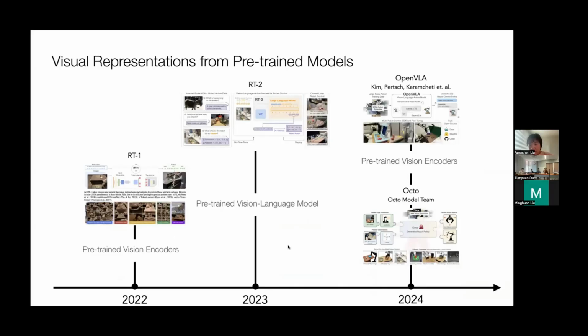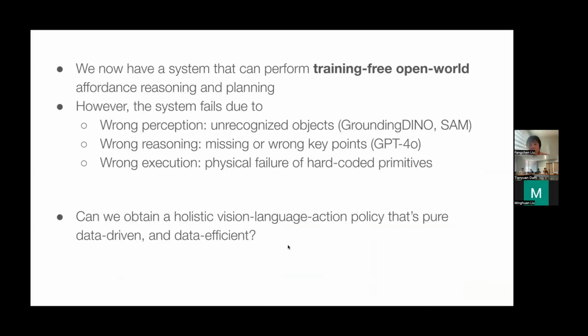Hi, Fangchen, can I ask a question? Okay, sounds good. For the waypoint, I'm wondering if you ask GPT-4V to label on 2D, then how do you know the height? If we want to wipe something on the table, is the waypoint always on the table? That's a very great question. We just hard code the height. We hard code maybe different quantized heights, like something on the table or something we feel is in the air. Like if we want to drop something, the waypoint is actually in the air. So it's some sort of hard coded stuff.